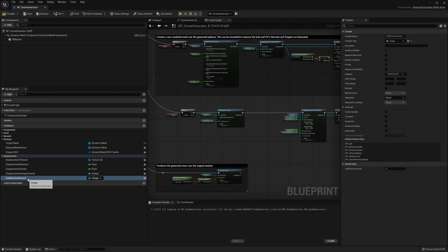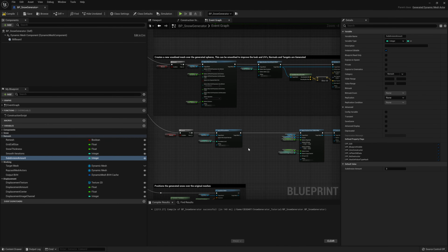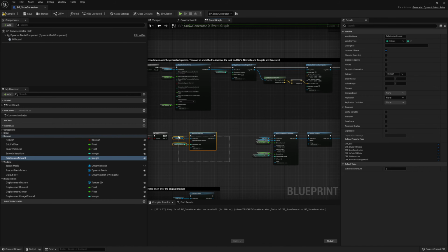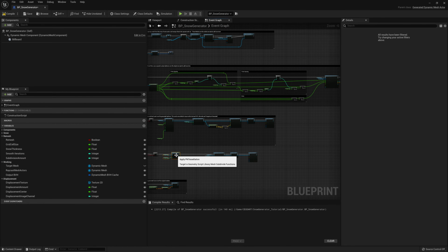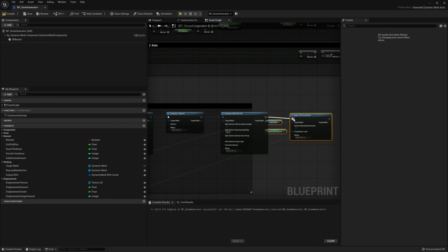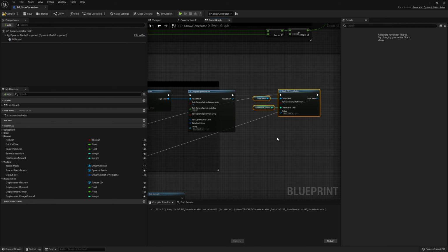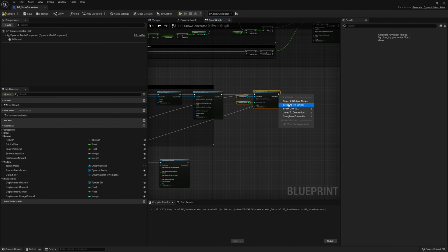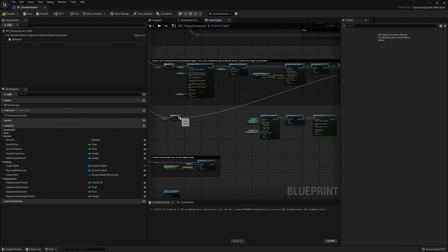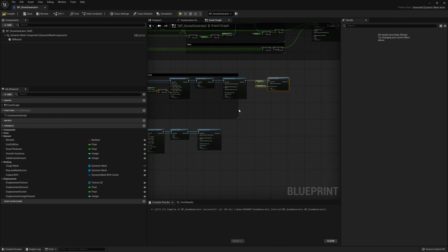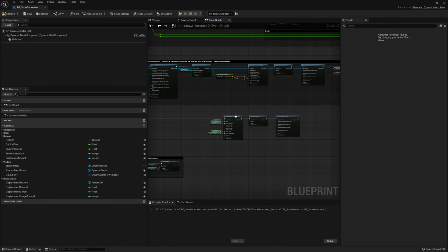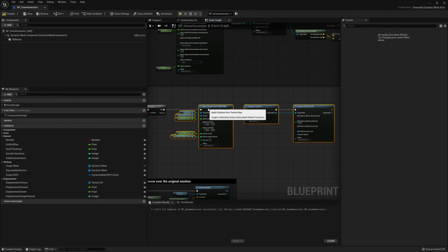And then what I'm going to do is move the subdivision into the remesh category. The reason for this is I think that we should have the mesh being able to be subdivided regardless of whether we use a displacement texture. So I'm actually going to move this up to after the remesh function. We don't want to do subdivision if we've not remeshed, because that would just subdivide the spheres and we don't really want to subdivide the spheres. What we want to do is if we use a remesh, then we want to be able to subdivide that remesh, and then once we're happy with the amount of polygons that we have, we want to be able to then displace that. So I think that works in a better way.